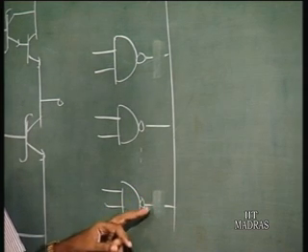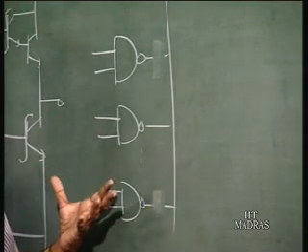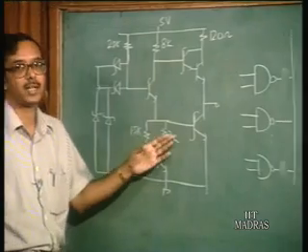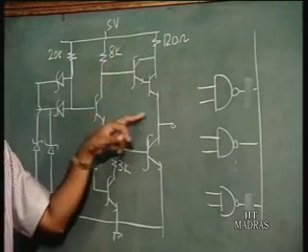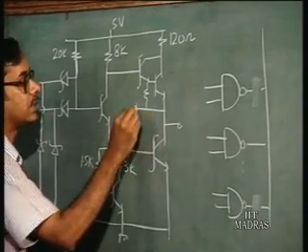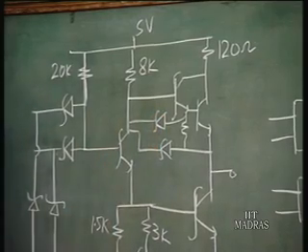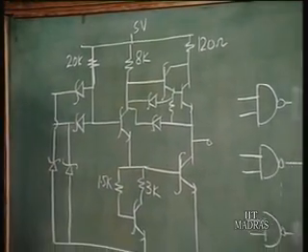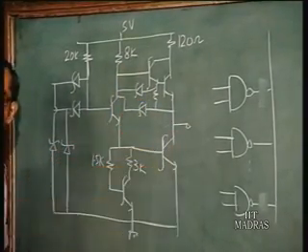So, this is possible only when this output is in the high impedance state. That is, that output is neither sourcing any current nor sinking any current, so as if it is open circuit. That is possible in this configuration here if you can switch off both this transistor, the pull down transistor, and also the upper half. Of course, I am sorry I missed out some; in the complete circuit, you have 2 more diodes here anyway. So, when you switch off this lower half, this pull down transistor, as well as the pull up, in that situation it is as if this is floating.